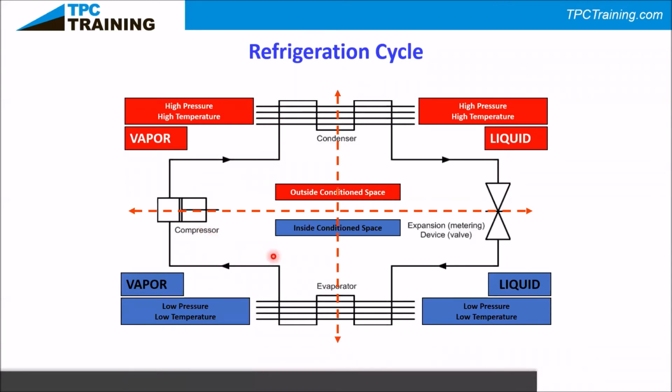But the airflow for the condenser and the evaporator: if we don't have air moving to our evaporator or moving away from our condenser, we're not going to pick up heat in our evaporator, and we're not going to give off heat in our condenser. So if you have a service call on a system and you're running a low pressure on your low side, your gauge is going to read about 70 psig for R22 and probably like 400 for your R410A refrigerants. If you're lower than that, 90% of the time it's going to be because there's some type of airflow problem.